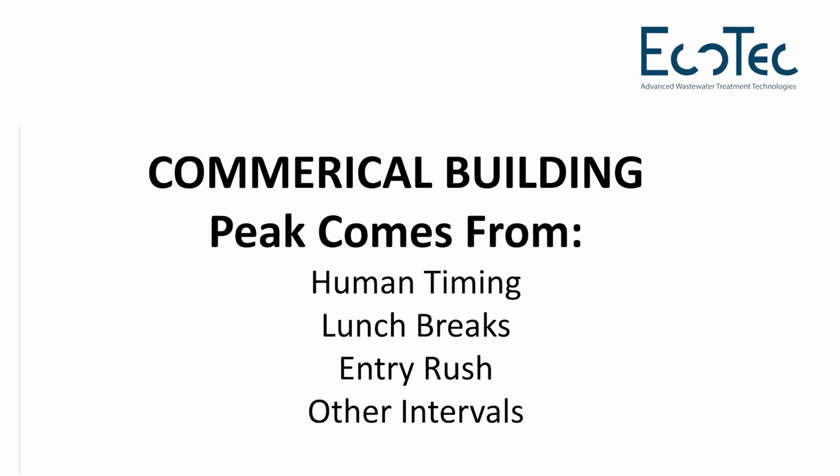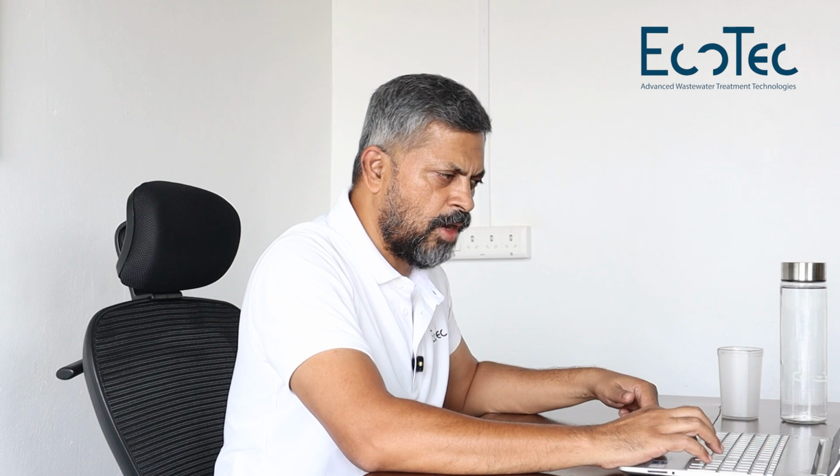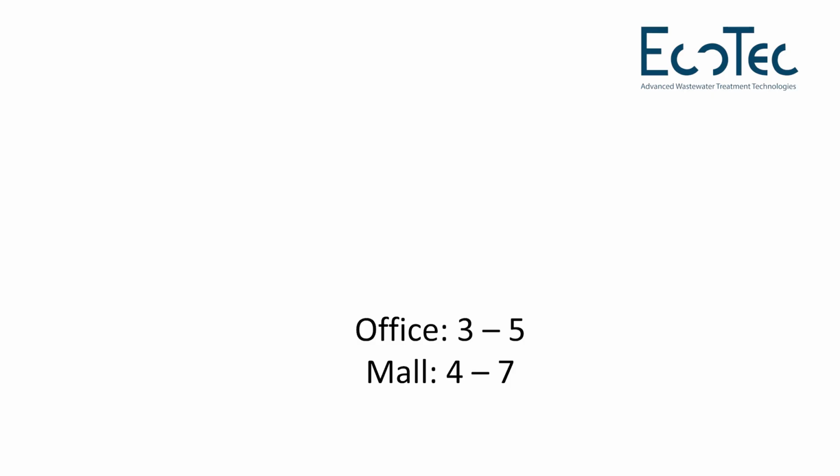Lunch breaks, again, are when there's a lot of usage of toilets and washing of hands and then washing of plates and so on and so forth. There are, again, times when people leave the office, when there is going to be a surge of water usage. In certain types of buildings, there can be other peak intervals during the day. And most commercial buildings are operated not 24 hours, but somewhere between 8 to 12 hours. All this has an influence on how we calculate peak factors.